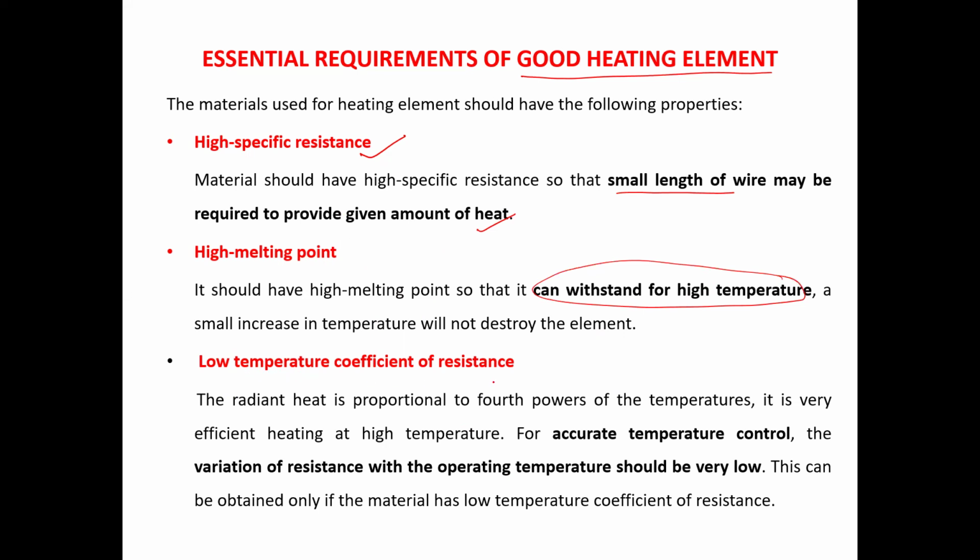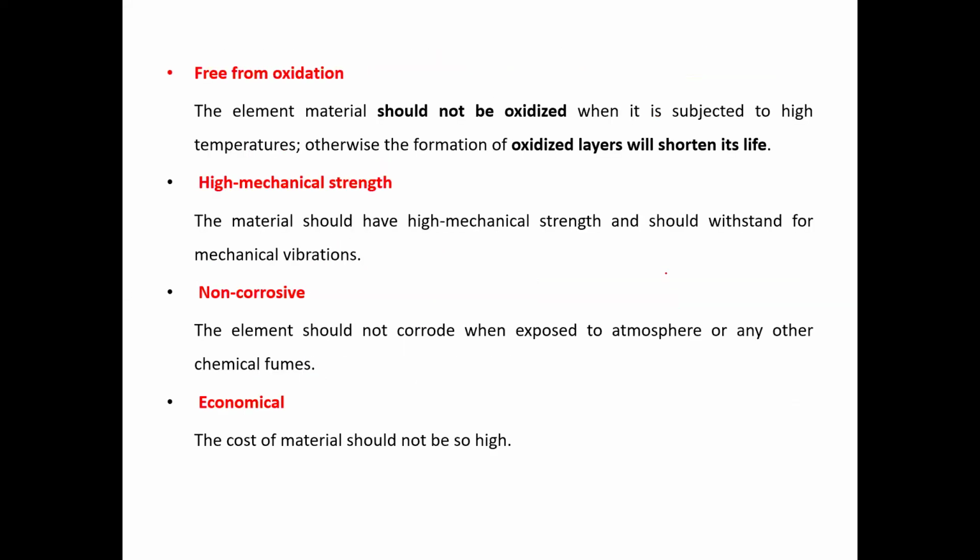For accurate temperature control, we can have a low temperature coefficient of resistance. These are the requirements of a good heating element. Free from oxidation. Don't neglect this point here. Free from oxidation in the sense that the element material should not be oxidized.